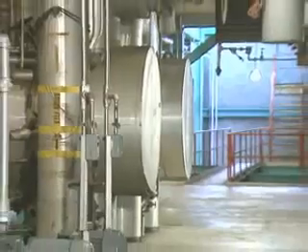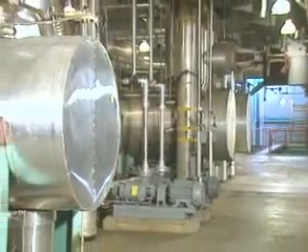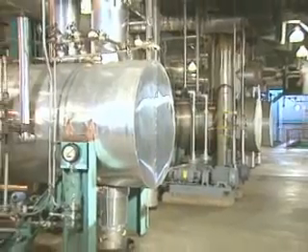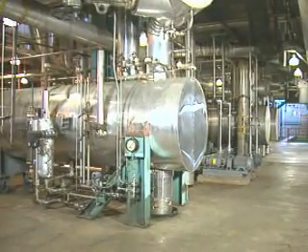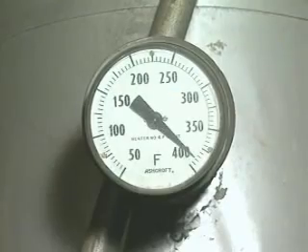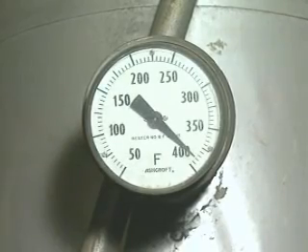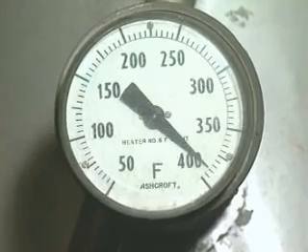Feed water heaters in many condensate and feed water systems are installed in trains or strings that are monitored as a unit during normal operation of the system. In this arrangement, the final feed water outlet temperature is commonly used as one way to monitor the performance of the heaters. The final feed water outlet temperature is the temperature of the feed water coming out of the highest pressure feed water heater on its way to the boiler's economizer.